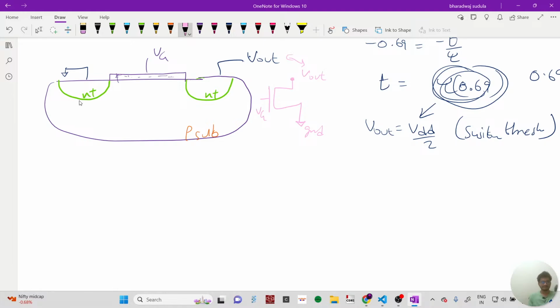And there is another terminal, that is bulk voltage at the bulk substrate body, and this is actually connected to source itself, and we can just connect this to source ground as well. And there is a direction, right? That direction can be easily identified by considering that this is a P substrate and we have an N channel, right?